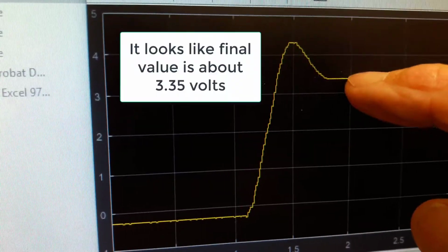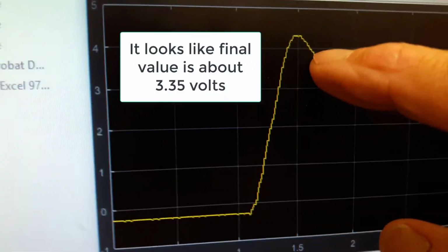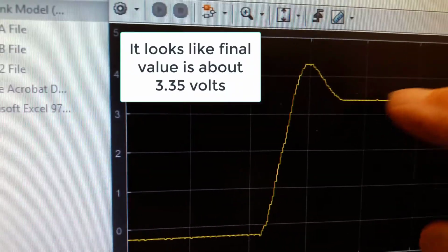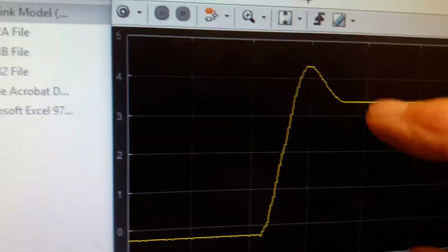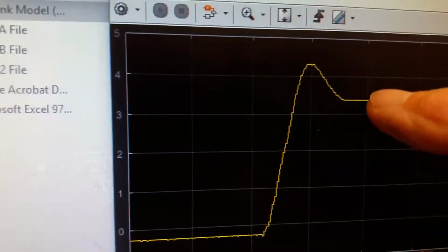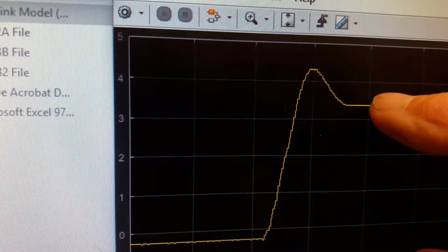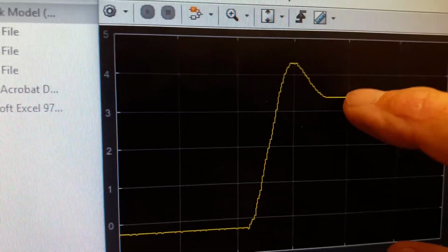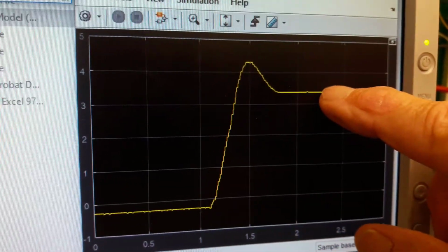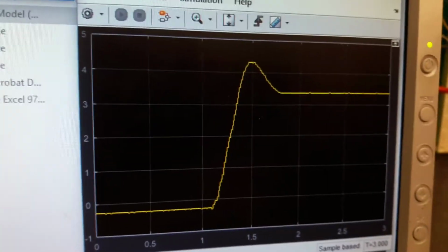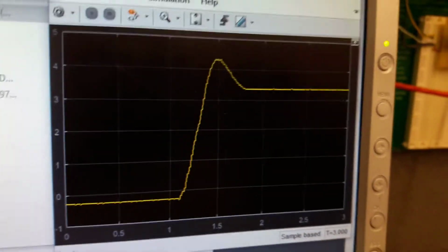The problem, though, is that you have a stiction range in here that this can settle around. If we had no stiction, it might not actually settle in this spot. There's a range that you need to find, and you really want to be in the middle of that range. And so we've come up with a way of dealing with that problem. So let me demonstrate that.